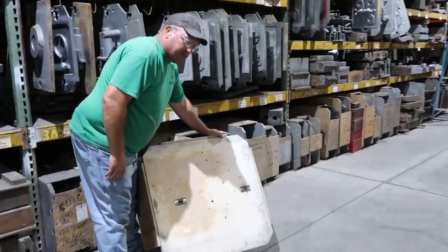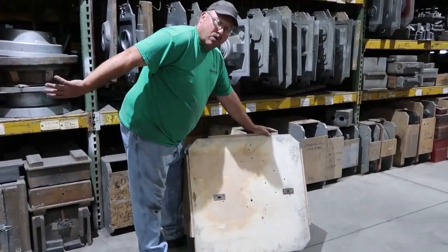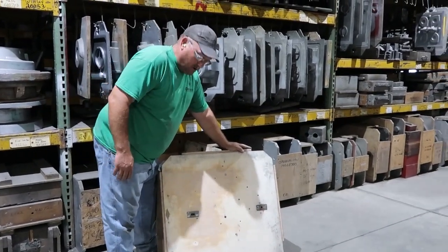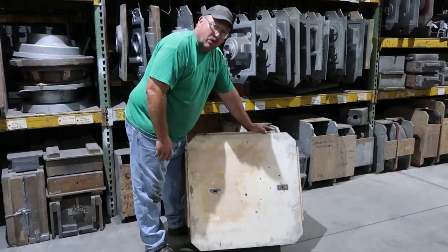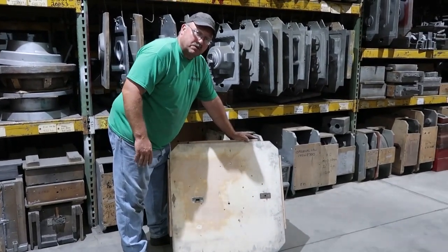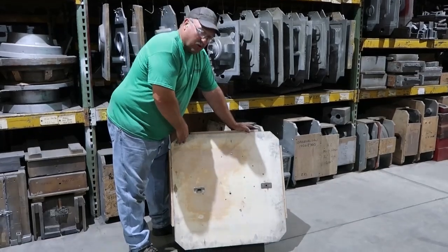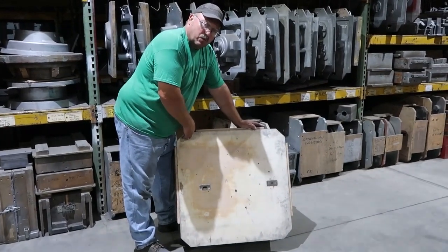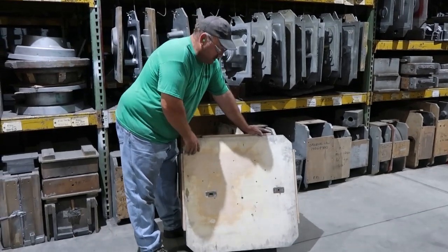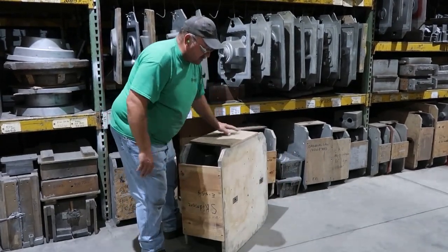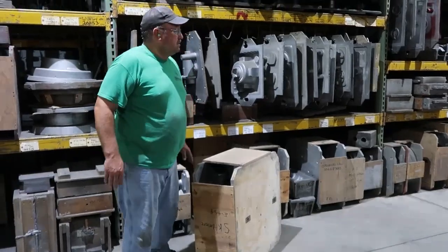We have a pin and slot setup. We have nesting boxes over in our production area. A pin and slot is how they go into the nesting box, how they get located so you don't get your cope and drag mixed up. We have inserts that are 22 square, 26 square, 30 square, and 36 square. That's what we call a rollover insert.